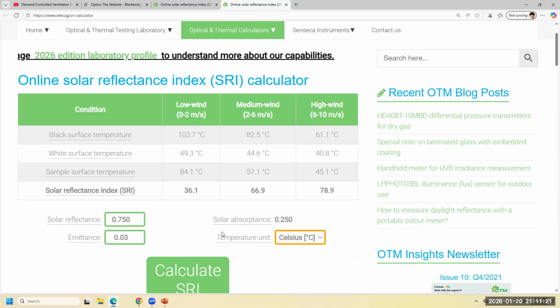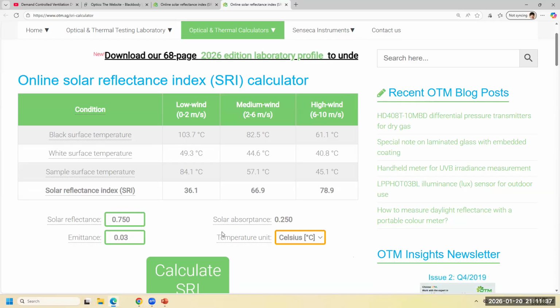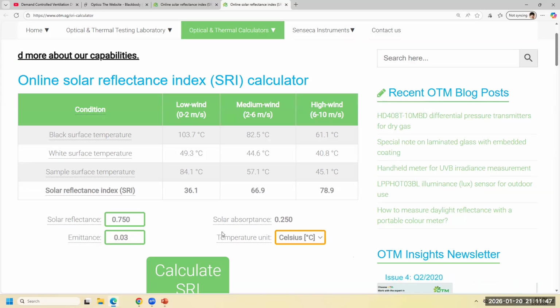Under the strong sunshine, although it knows how to reflect the solar energy, the sample surface temperature is still hot, like 84. So the concrete and the metals, the main building construction materials, absorb or trap heat in our outdoor environment. So consider this for building construction.